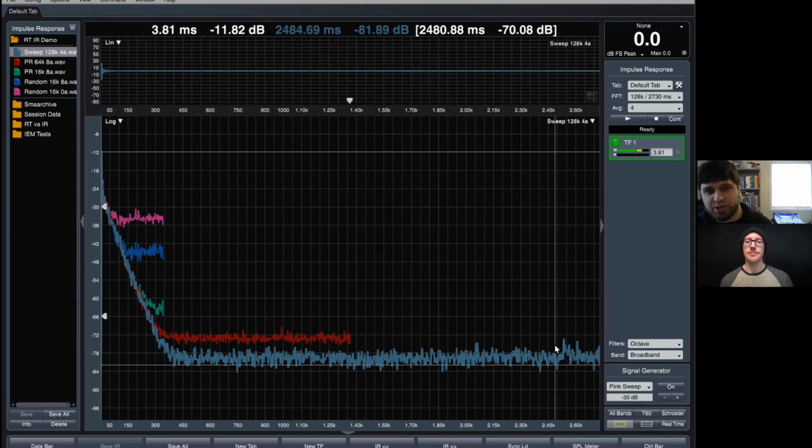Now, again, on a super good linear loudspeaker, this doesn't really get you all that much because you don't have that much distortion in your measurement to begin with. But if it's a speaker that's working really hard toward the limits of what it can do, you have high distortion in there. This can get you, like we gained an extra 6 dB or so by doing this.